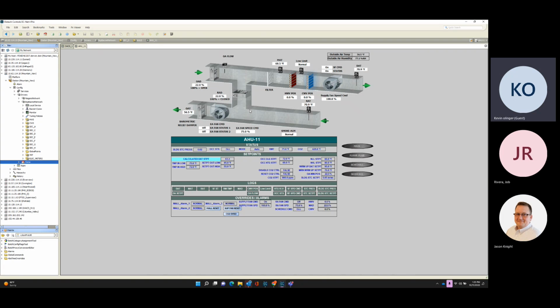Traditionally, any air handling device over 2000 CFM requires a duct detector. And then typically that duct detector, detecting ion or smoke, will be hardwired to the air handler to force that single air handler to shut off if it detects smoke or ion. And then it's tied into the fire system, so obviously it tells the fire system that there's an issue. And that more than likely is just a trouble or supervisory at that point.